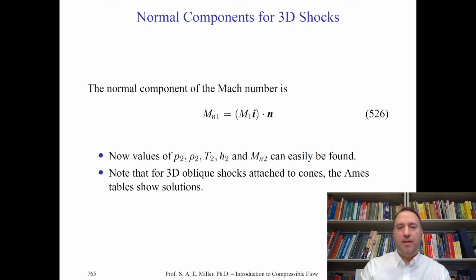For example, you can handle these problems by taking the tables and doing table lookups. Or you could devise numerical methods and solve the equations numerically, which are also shown in the Ames tables, but not my particular equation sheet. This way you can at least approximate the values. In reality, these problems are typically today solved with full computational fluid dynamics solvers, which solve the full Navier-Stokes equations